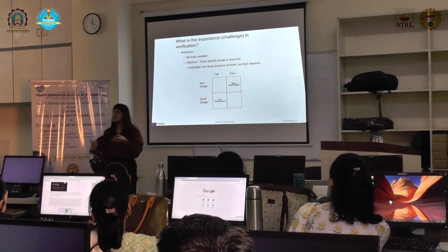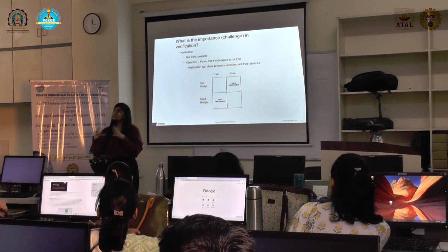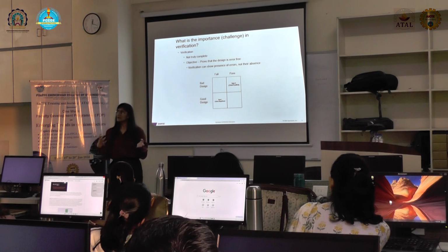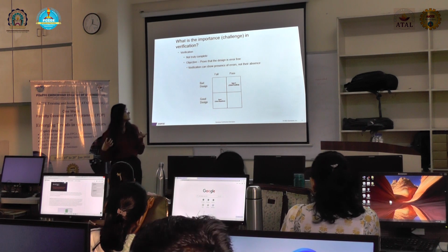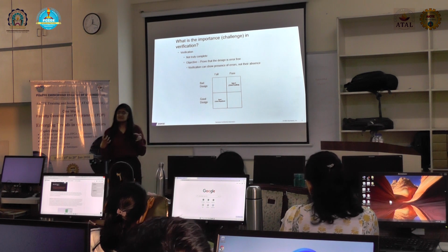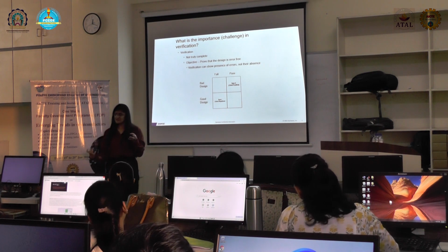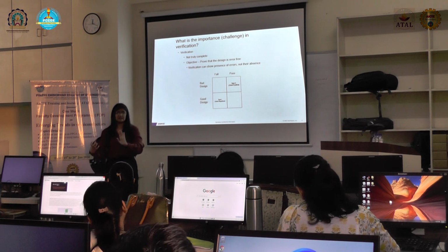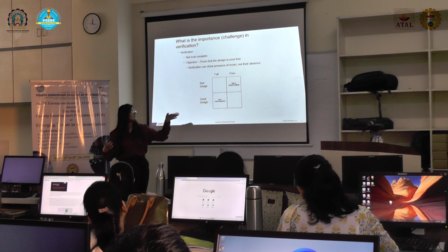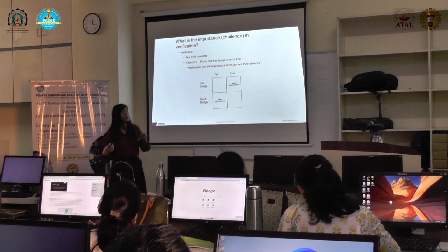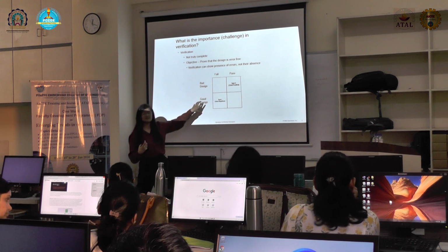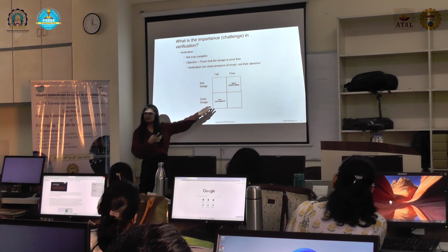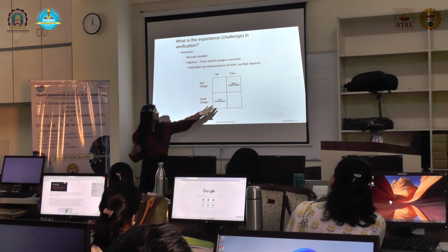VFMs are verification functional models. So it has a driver logic. It has some specific logic which mimics the driving or monitoring part of the test bench. So we use those VFMs, VIPs, and we check. In those cases, there could be chances that the VIP is not behaving correctly, while the design is correct as per the specification. That will show that your test case is passing, but not due to the design, but due to other elements that we are using. So that could be considered a good design because we need to fix our environment according to the design.